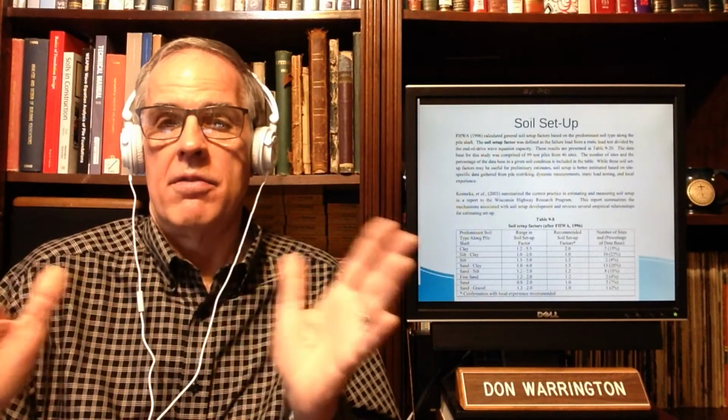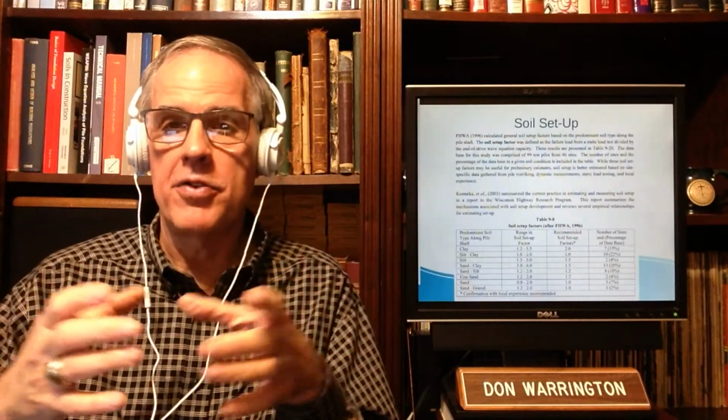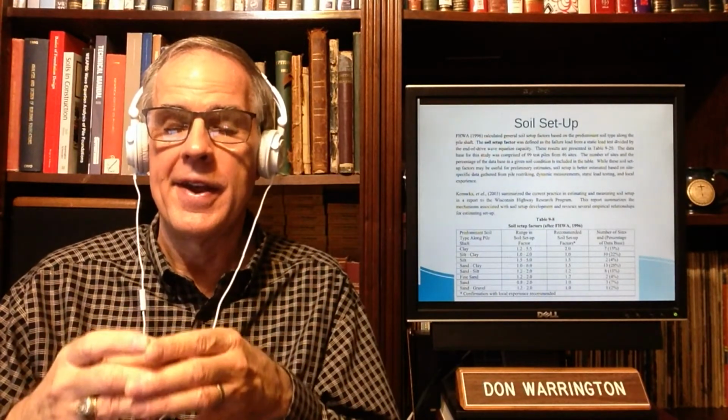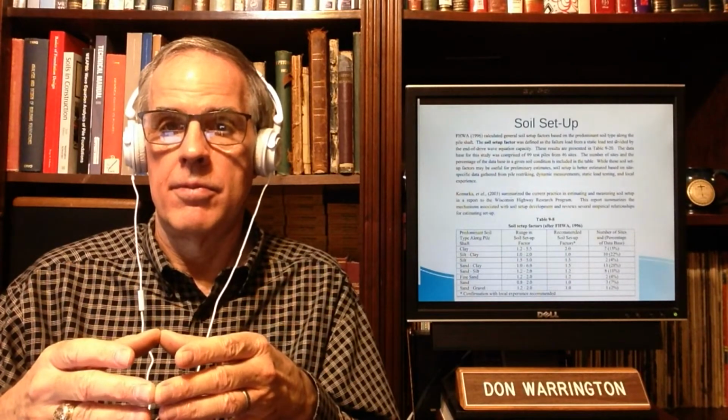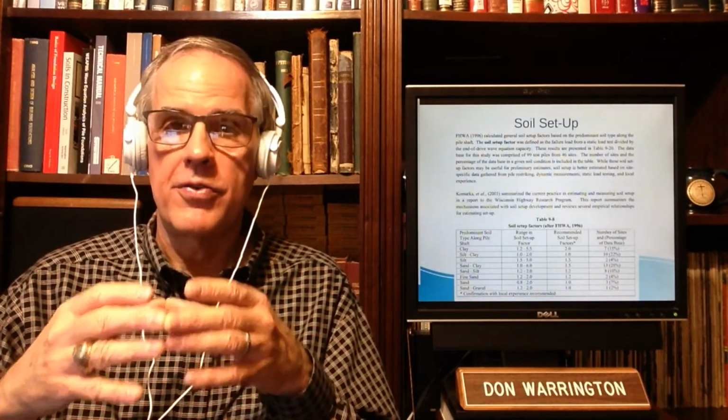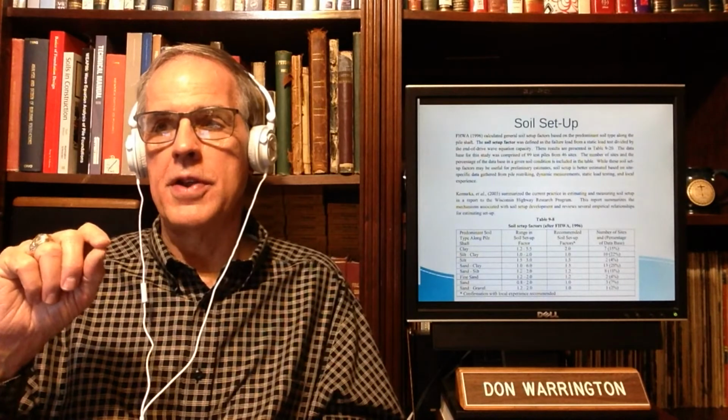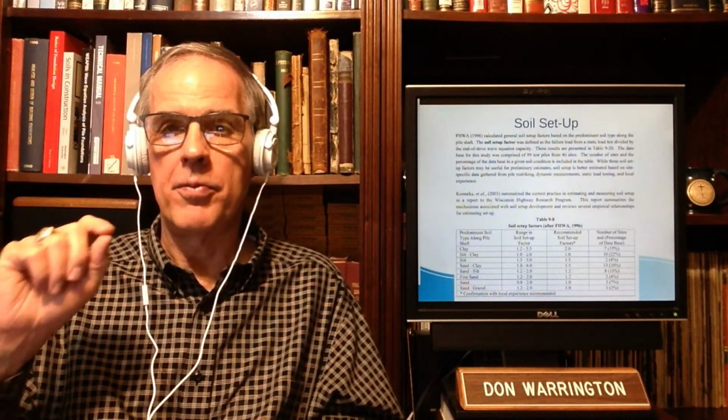Not because the water table is going up and down, but because the pore water pressure has temporarily been raised. When that happens, your effective stress goes down, but that doesn't last forever. Eventually, those pore water pressures are going to dissipate and things are going to get back to some kind of normal, and you're going to get a capacity increase. In other words, the effective stress around the pile will increase again as the pore water pressures drop, and when that happens, your pile capacity increases. This is referred to as setup.